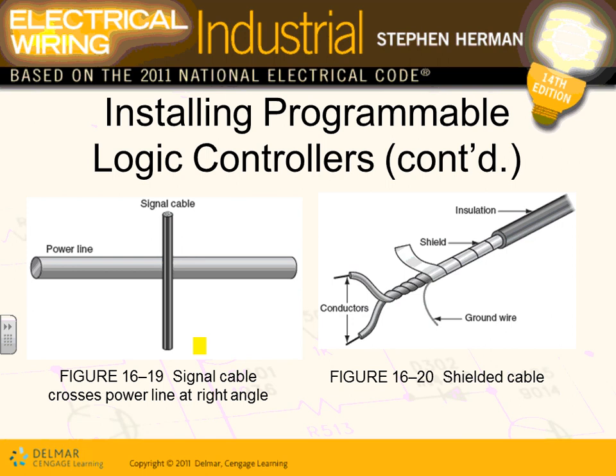So here's your shielded cable that you use so you minimize the interference. You cross the power line with a right angle like this, so you don't have induced voltage into the shield. Then you minimize the induced voltage. The last thing you want to do, guys, is have a power line here and a control line next to each other.